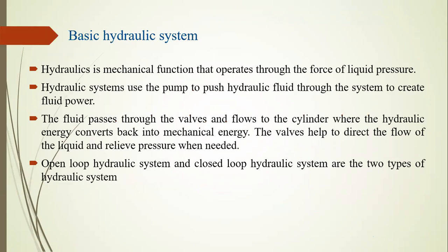What is the need for a hydraulic system? What is the requirement for a hydraulic system? Why do we use it? How can we convert energy from one form to another? The hydraulic system is a power transmission system. The basic hydraulic system, called a power transmission system, converts mechanical energy through a pump. The pump flows pressurized hydraulic oil to the actuator, and the actuator converts it back into mechanical energy.